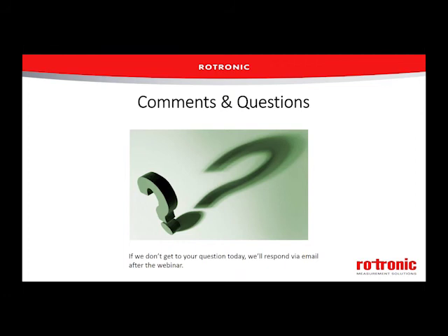Here's a question from George. His question is, does the data refresh rate or the response time affect uncertainty? It can affect uncertainty, especially if you've got a very fast moving environment. Potentially your instrument is not sampling fast enough to get all the peaks and valleys that are coming in. So it can absolutely have an impact on your uncertainty, especially if you're trying to take an average over a long period of time. Your refresh rate needs to be adequate to actually see what's going on.